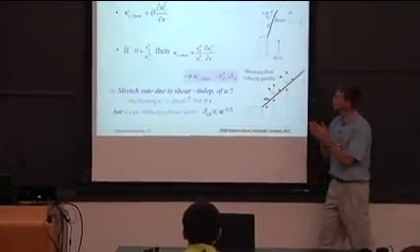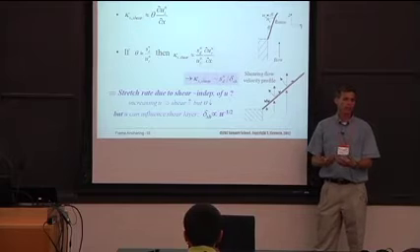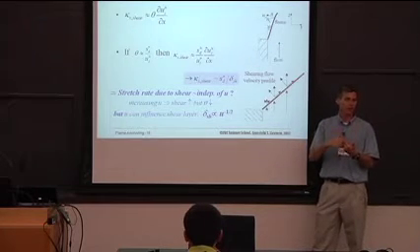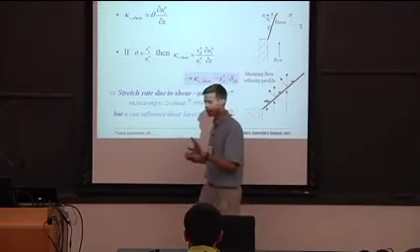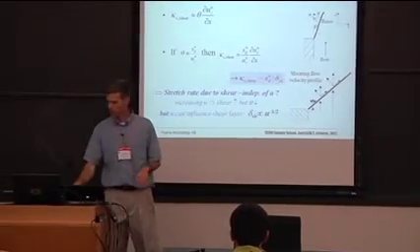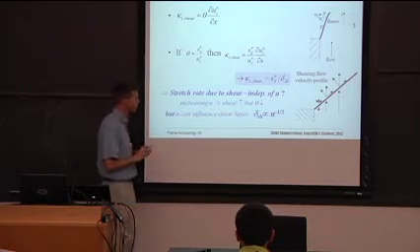So if you double your flow velocity, you double your fluid mechanics strain. All right? But you halve the flame angle. Theta goes down. The two exactly cancel. So the key point here is that flame stretch and fluid mechanics strain are not the same thing, and there can be some very interesting relationships between them.